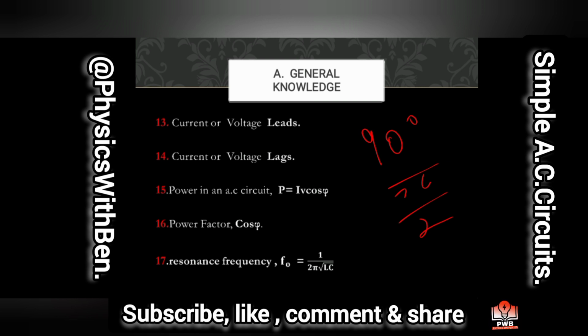Examiners may ask you to calculate the resonance frequency. This is the symbol for the resonance frequency. There are so many conditions that lead to resonance in simple AC circuits. One of them is that when the capacitive reactance is equal to the inductive reactance, XL is equal to XC. That will give us this particular equation here.